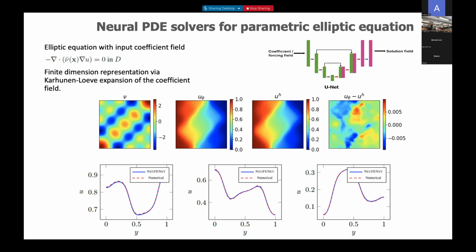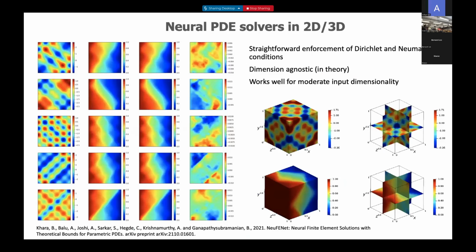And then we see that one of the challenges when we explored physics-informed networks was the imposition of, say, Neumann conditions, right? It's easy to impose Dirichlet conditions, but non-trivial to impose Neumann conditions because of the Lagrange parameter that I talked about. Right? So here, because it's a grid-based approach, it's very natural to apply Neumann conditions, and so we see several line cuts across, and we're able to solve this strategy.